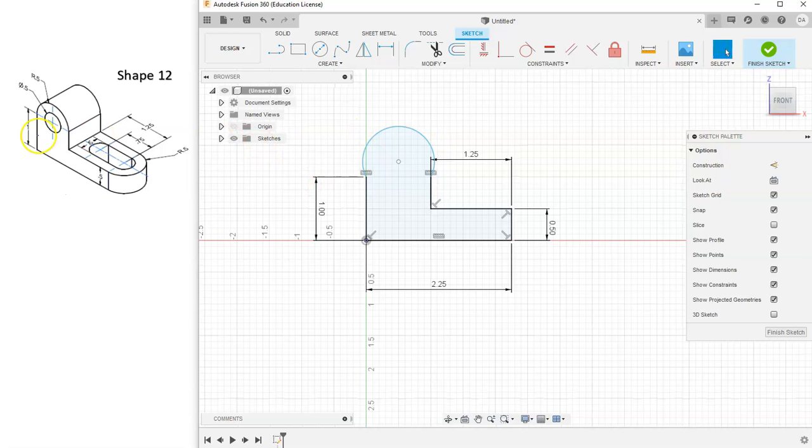And what is the radius of this arc? Well, it's a radius of 0.5. And so if I grab my dimension tool and I select this arc, remember, anytime you are dimensioning a partial circle, it'll give you the radius. Anytime you dimension a full circle, it'll give you the diameter. And so I'm going to select, and it's asking for the radius is 0.5, and hit enter. And now we have a fully constrained sketch. Now, I could have, let me hit Control Z a couple times.